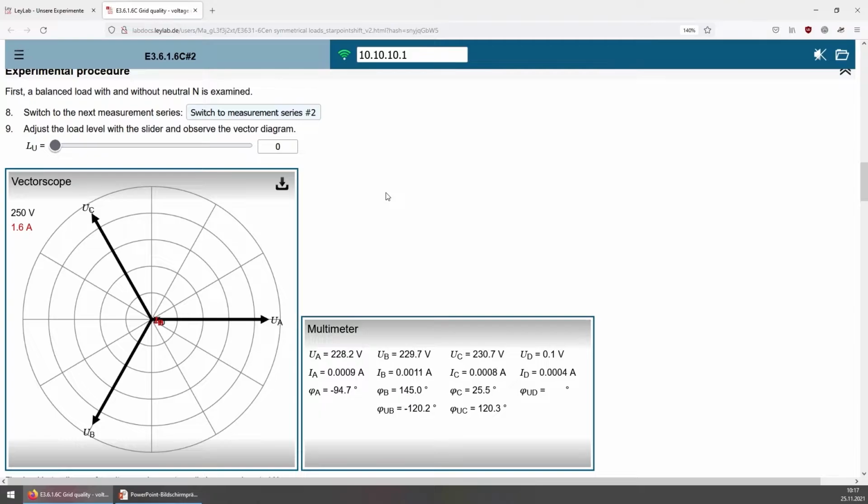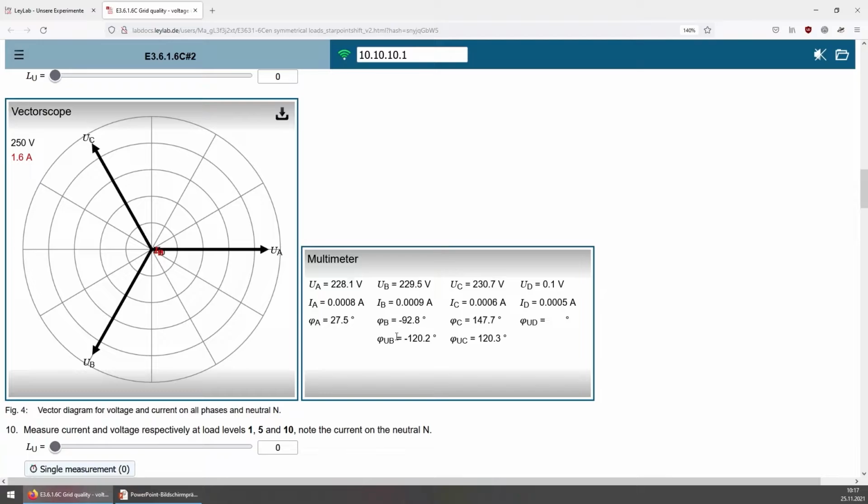And when the series is loaded, you can see a vector scope of each phase. Line 1 corresponds to UA, 2 corresponds to UB, and 3 to UC, as you know it. We have a phase angle of 120 degrees between each of the phase line voltages. And as expected, we have a voltage of about 230 volts, already with a slight imbalance coming from our grid here.